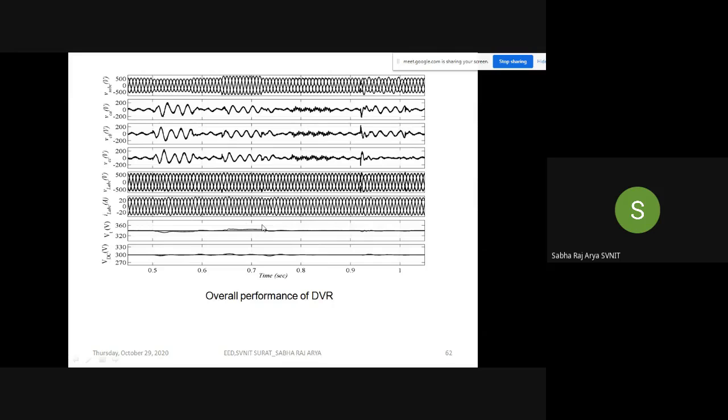It means we don't have proper PI tuning, and we cannot do proper PI tuning by random trial and error. For that we need to develop some algorithm for how we can design the PI controllers so that we have a good response. We should know at least a guideline for how to choose the values of Kp and Ki. Otherwise, if you put in random values, it will take me 1 day, 1 week, 1 month. To reduce the time, maybe we can develop some algorithm for tuning of Kp and Ki.